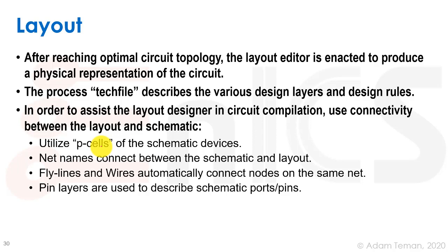We can use net names to connect between different areas of the schematic and the layout and help us drive this, show flight lines where things are supposed to connect to each other, and even automatically route things. And we can use pin layers to describe schematic ports and pins to pass LVS. When you do this in hands-on work, you'll learn how to do it. I will not discuss this in the lectures too much, but if you do labs that use these different tools, you'll understand what I'm talking about.